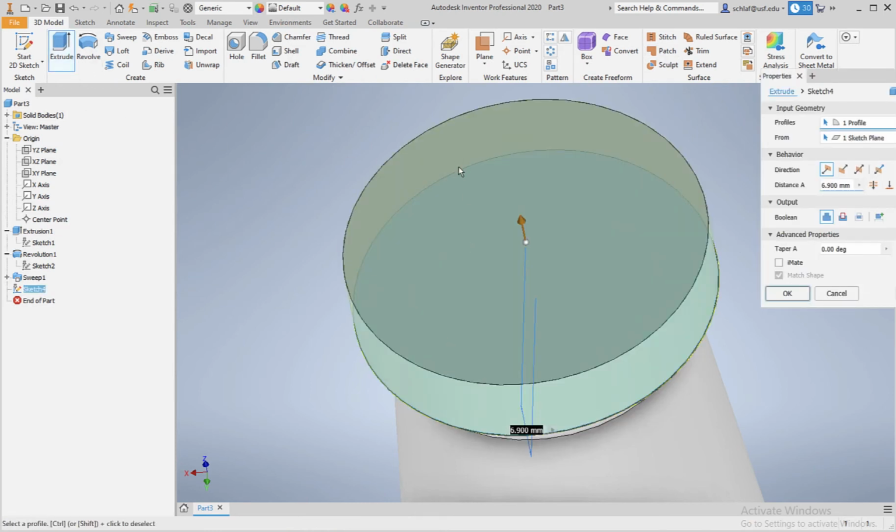Since we're extruding in the Z direction, we need to use a multiple of 0.3 to make the printer happy. And because now we're going over an empty space, we need a few printer layers in order to get a smooth surface, because gravitation will mess up the first few layers, and they will sag a little bit.